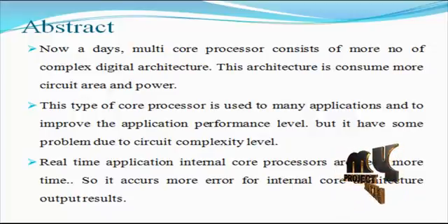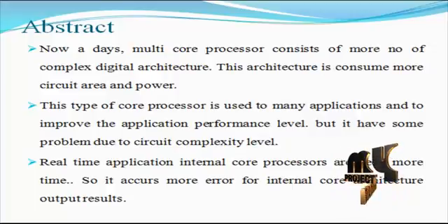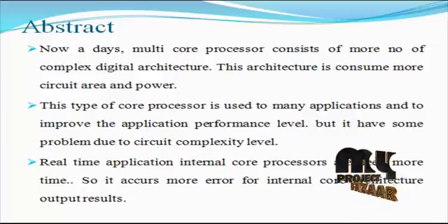For these designs, a test access mechanism is needed that allows the core to be efficiently accessed and tested. Using a general embedded core test methodology such as IEEE 1500, cores can be wrapped to prevent interaction with outside data sources, allowing the test for a single core to be generated and applied to each instance of that core. IEEE 1500 provides an efficient solution for testing cores, allowing a parallel test access mechanism.